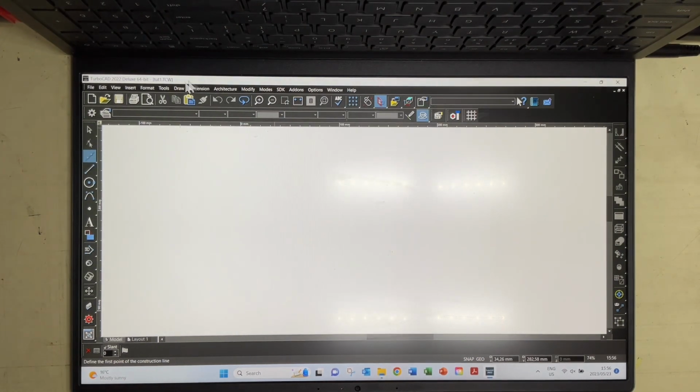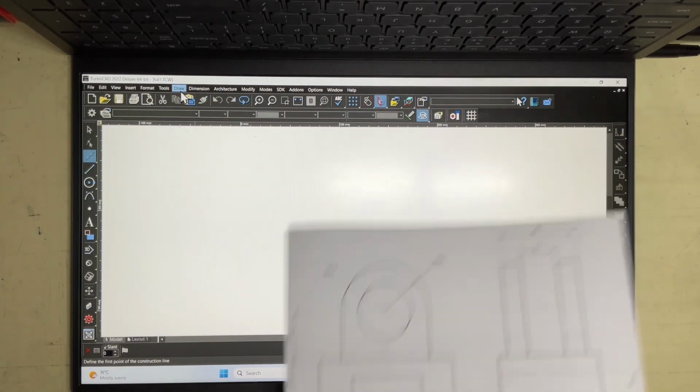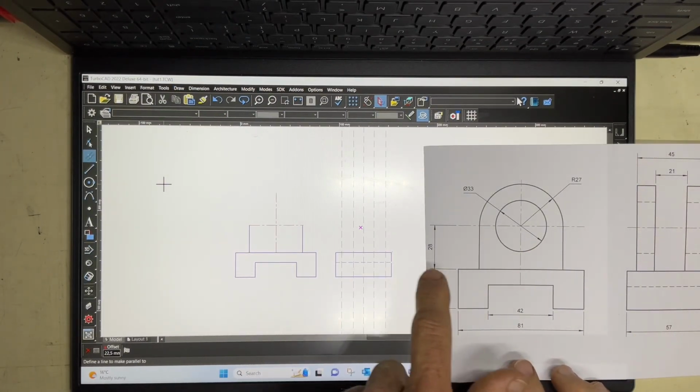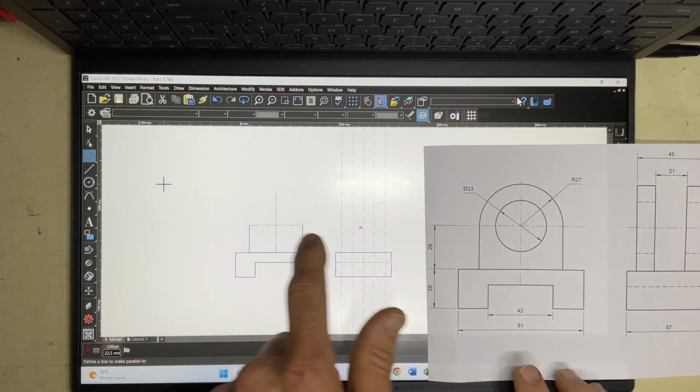Press OK, and then you'll see over here that it will say TUT1 at the top there. That means that this drawing that we're going to start drawing over here is going to be TUT1, and I can then start drawing all of that stuff in there. Right, see that I've basically drawn out the base part of this story over here. I've got my center lines in place.